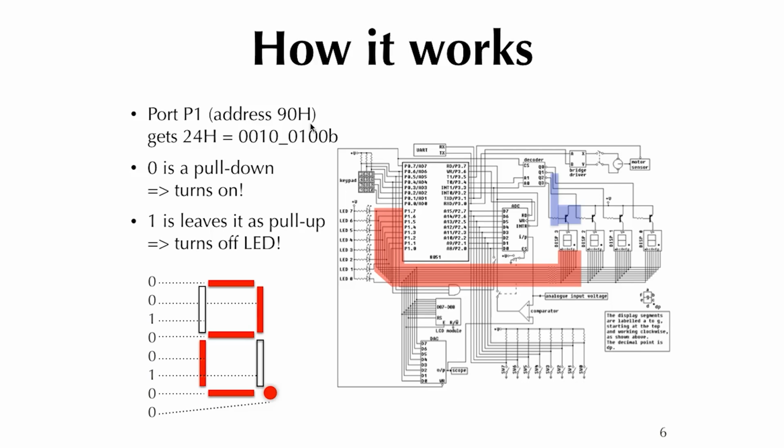All right? So if I write to P1 as a special function register, which is at address 90, then what happens? Yes, there is a little register. It remembers the value you put in. But as a side effect, the bits that you put in show up. So you can measure, you can put a probe. Is it high voltage, low voltage? Or you put a light on, light off, right?